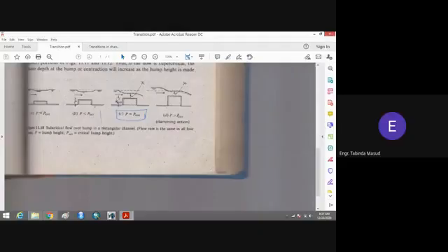Instead of decreasing this depth of flow, the level of water at the upstream side will get increased, and this is known as the damming action. Damming action means that it is going toward the situation of a dam. What is the function of the dam? The function of the dam is to store water in a reservoir at its upstream side. So if you are increasing the height of the hump, what are you going to do? You are going to increase the level of water.